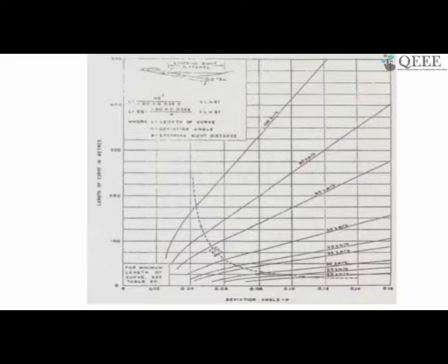Another question is, which curve will be provided? It depends on your gradient, which curve is needed there. So in mountainous terrain, both types of curves are going to be there. Another question which I received: if we provide small trees on the median of a valley curve to prevent the glare of headlights, then there is no need to calculate the length of the valley curve for headlight sight distance.